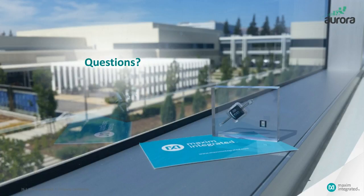So it all depends on the complexity to integrate. Our power point tracking and energy management is not dependent on monitoring like some other solutions are. Each cell string optimizer operates independently, so there's no requirement for it. We don't feel that the payback for cell string level monitoring is high enough to justify it as a core part of the system.